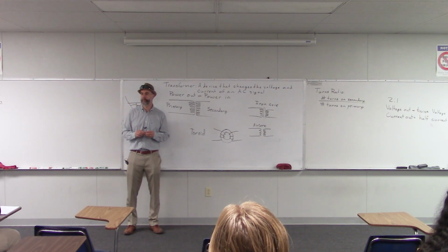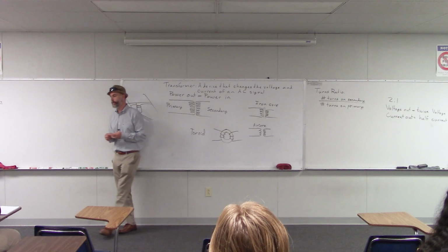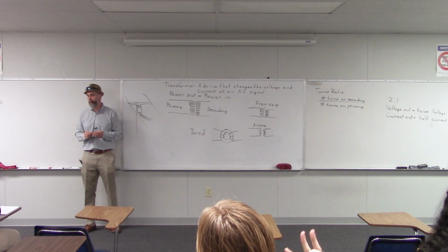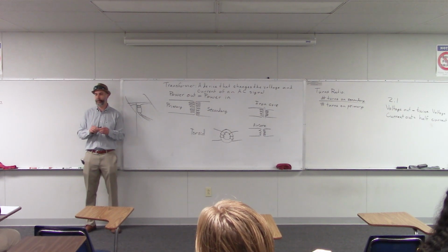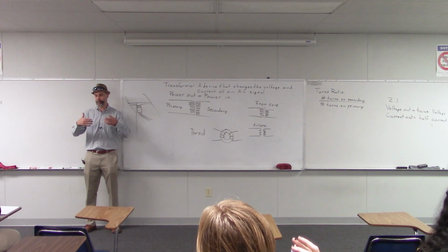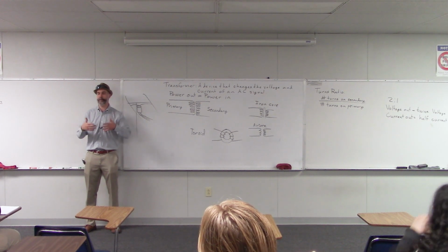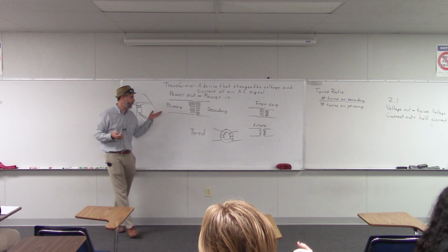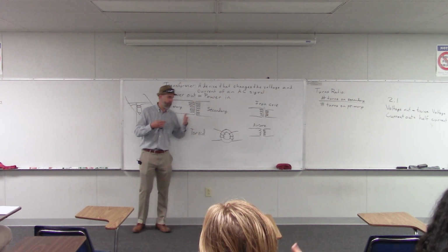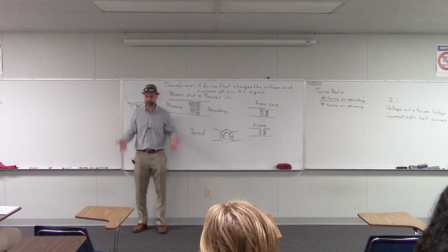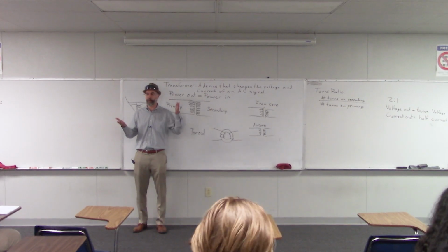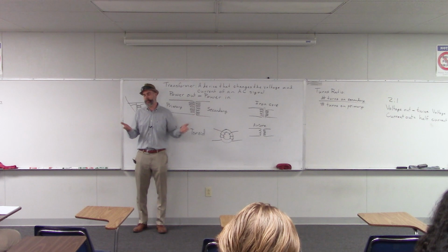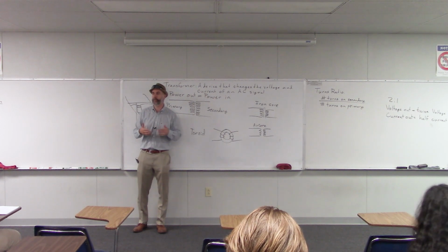So current affects efficiency? Yeah, essentially, the more current you're trying to transmit, the less efficient your system is going to be. So instead of transmitting lots of current, with the AC signal you can increase the voltage, decrease the current, and then be more efficient.